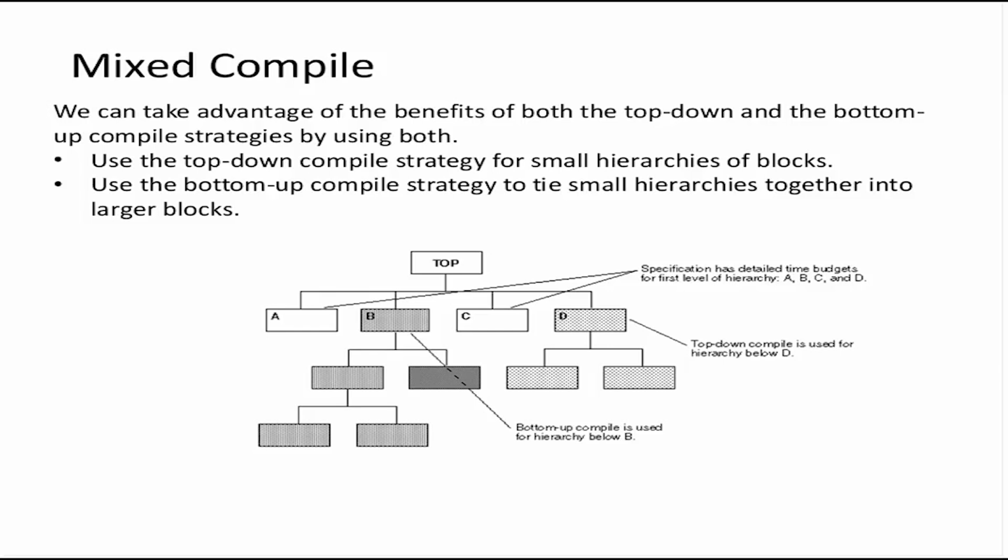So at a USB level or a CPU level or an MPEG decoder level, it is a top down synthesis. But at a chip level it's bottom up synthesis, meaning that USB is synthesized already, CPU synthesized already, MPEG decoder is synthesized already. We just read in these netlists at the top level and do a top level compile, assuming that the top level will have some glue logic in our case.